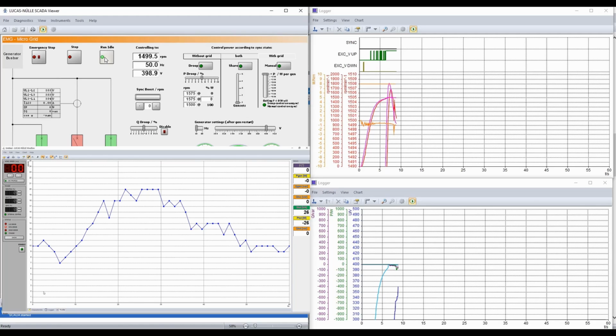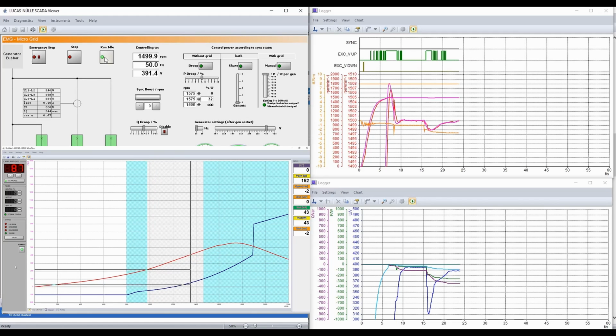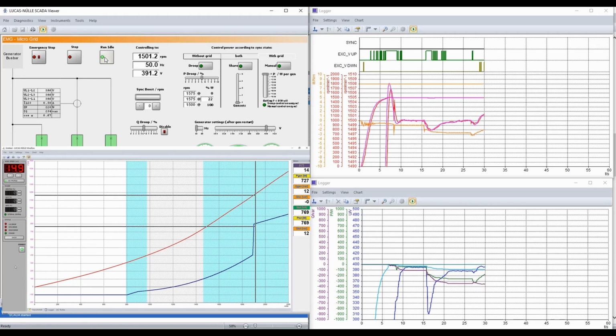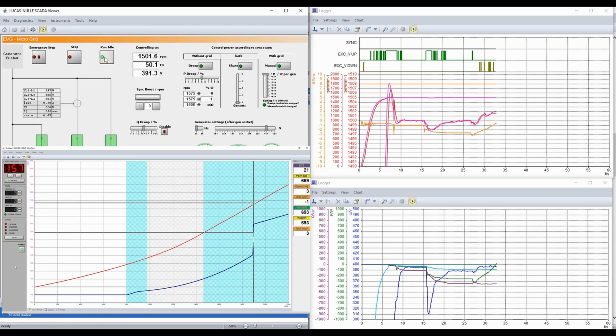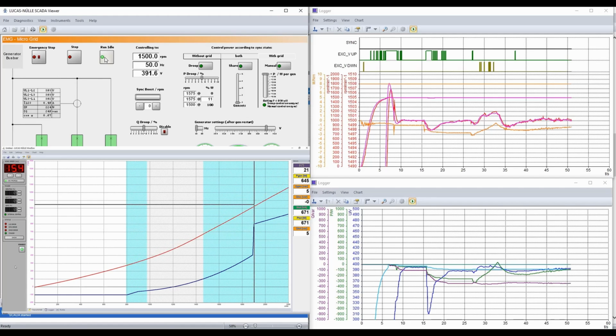Once connection between both systems has been started, the load will be shared, depending on the wind profile. Observe in the loggers that the primary system takes over the power supply of the load when there is not enough wind. Alternatively, when the wind is strong, the primary system reduces accordingly its active power supply. Observe that the changes to the wind speed translate to changes in the active power supplied by the wind turbine. The reactive power is supplied by the primary system. This behaviour is clearly seen in the SCADA logger of the primary system.